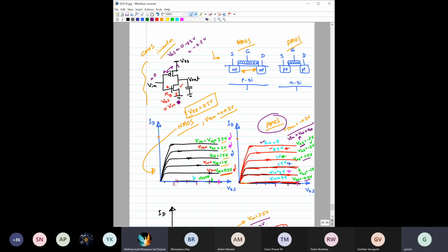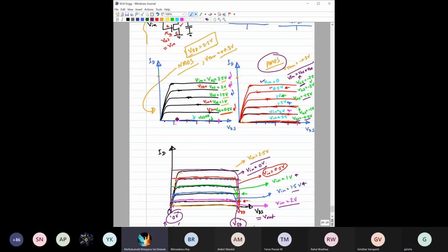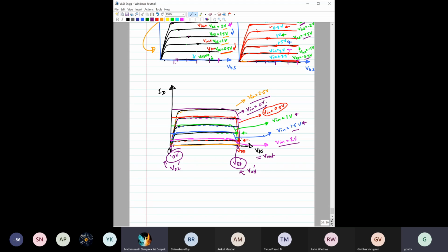So this is about static power dissipation. So no static power dissipation, right? I am saying steady state means basically you are not changing the input. Okay, input is either fixed to 0 or 1. It is not switching, right? So that criteria is also fulfilled. No static power dissipation. V out minimum voltage is 0, V output maximum voltage is equal to VDD. So that is also satisfied, right?